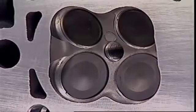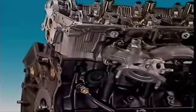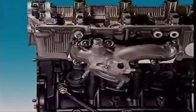Similarly, two exhaust valves mean the cylinder can be designed with larger exhaust ports, which provides a freer flow of exhaust gases out of the cylinder.